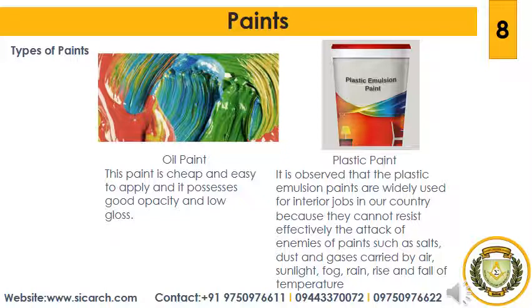So the success of paint will depend on the quality of plaster and the characteristics of the base surface. The surface to be painted should be cleaned of all dust particles and rubbed with sandpaper if necessary. The leveling putty should be applied if required. So the third one is about brushes.